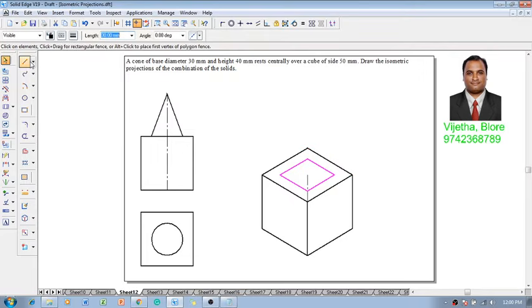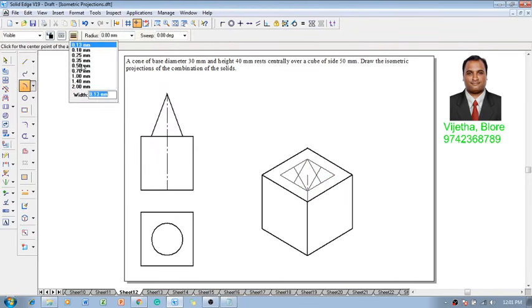And once we get this one, this thickness is supposed to be reduced to 0.13, and then make use of a line command with a thickness of 0.13. I'm going to complete the construction of a circle in the form of an ellipse, using the technique called the 4-arc ellipse. Now I'm going to show you how to do the same.